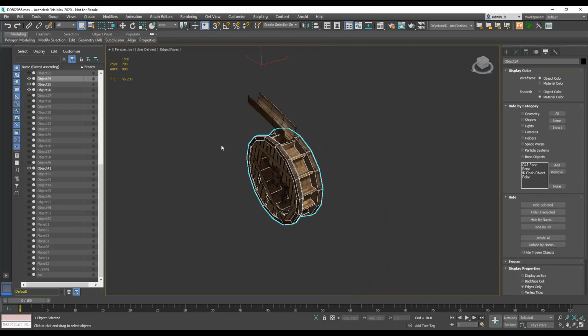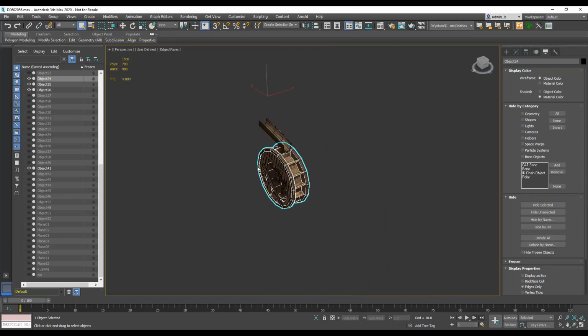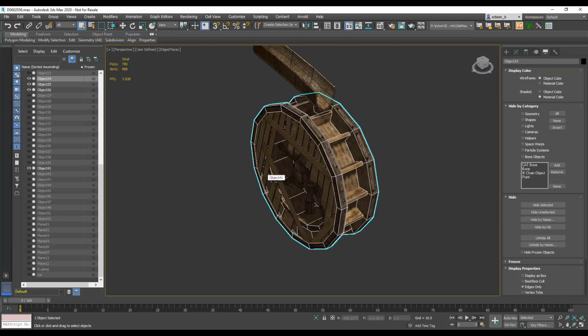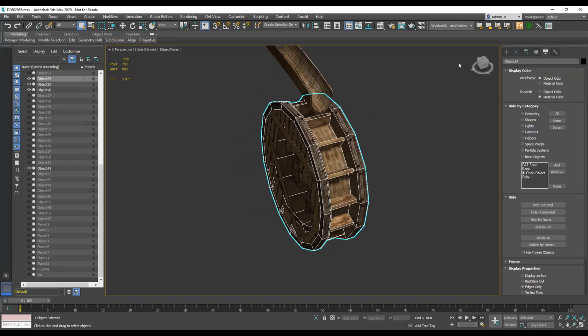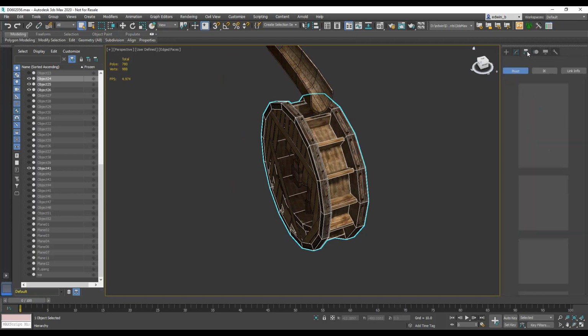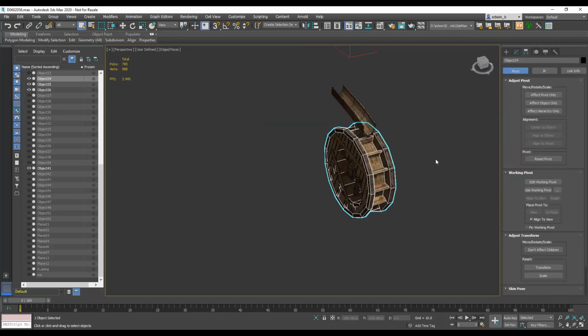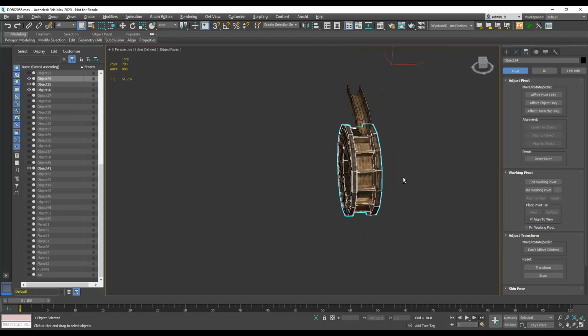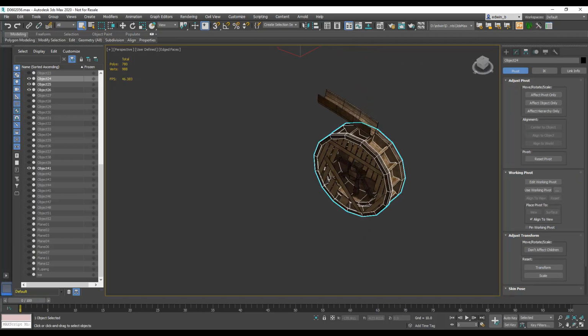So I did that work, I did adjustments, and the next thing that is also very important, and that we always see with files you download from the net, is that they don't care at all about pivot points or objects, how they are aligned, or normals, and all this crazy stuff.